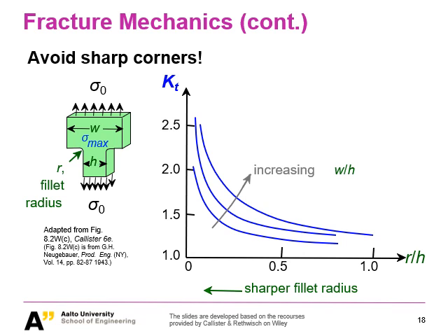So what is it? This can be applied to avoid sharp corners. Why? Because sharp corners will have a very small rho t, here it's r, right? It is this radius with the fillet. Because this small radius will make your geometrical factor very high, and that will amplify your nominal stress to the local stress at the crack tip.